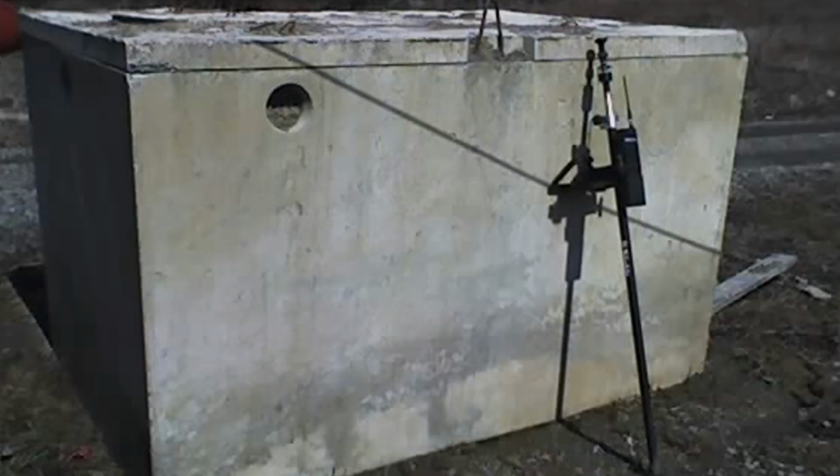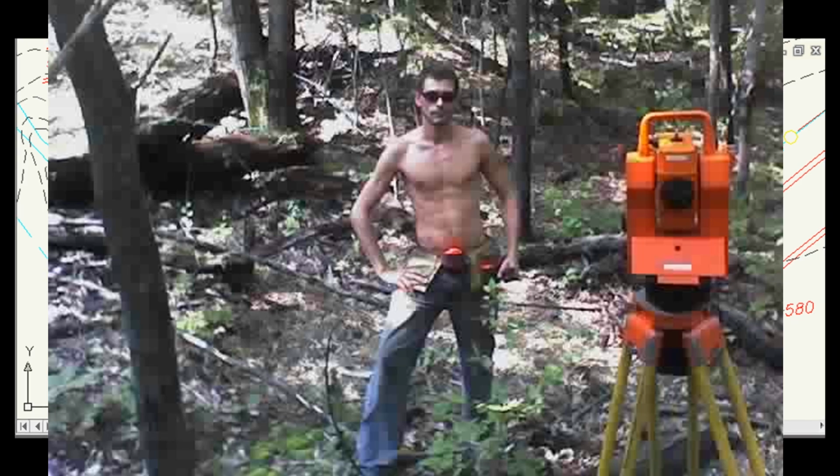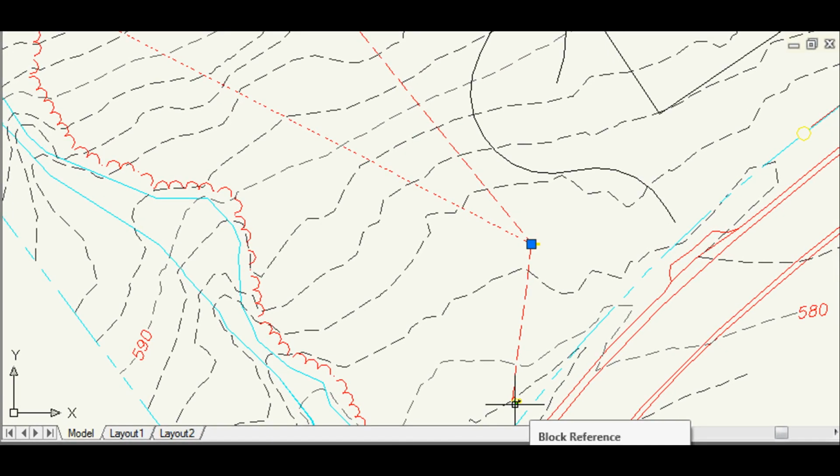One technology it uses is infrared, and that's so it can track the prism on top of the staff or on the back sight or foresight. Those are the target points that we use to shoot precision. The other one is actually used to take measurements, and that uses laser. And laser is very precise because we're using light, and so it's very hard to distort that distance measurement.